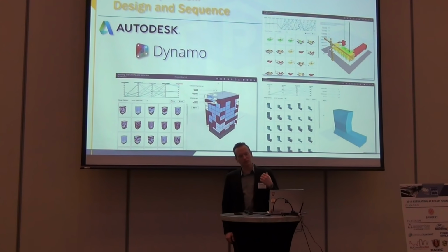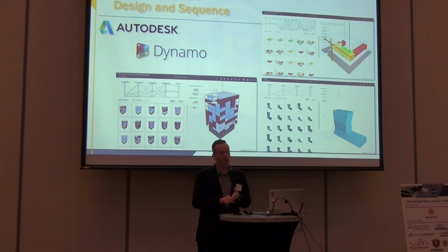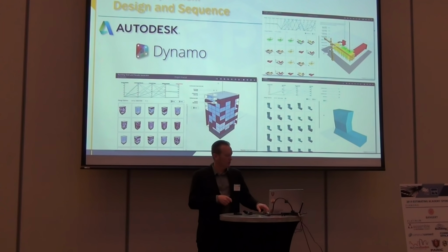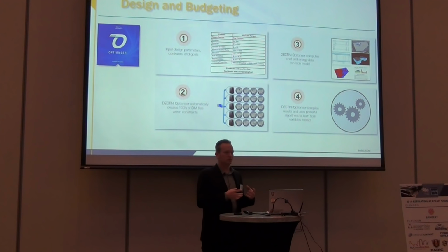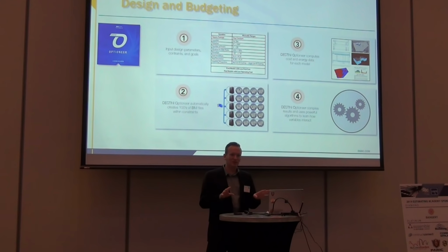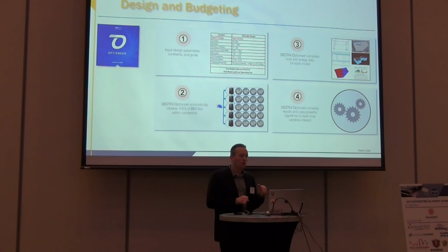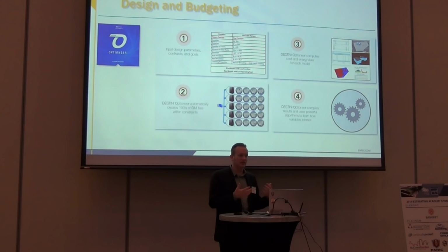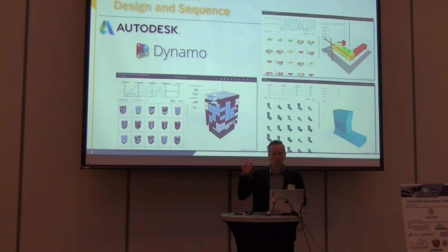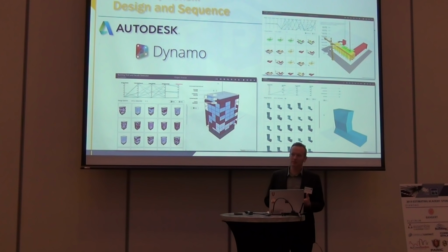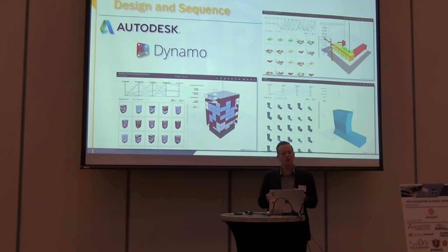If I can load some basic rules into tools like Dynamo and Revit, well, using those two together, there's another product called Optioneer that you give some basic rules. And I'm not trying to make this sound like it's super easy. This is not exactly like an easy button. But once you create it once, you can use it again and again and again. What this allows you to do is take a look at a project and say, what different types of configurations could I use on the job site? How many floors, how much glass area versus brick area, all those types of things.